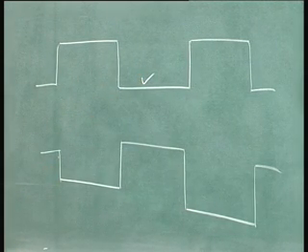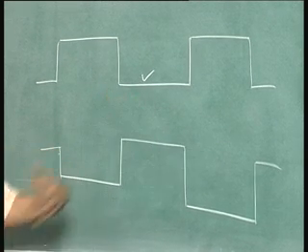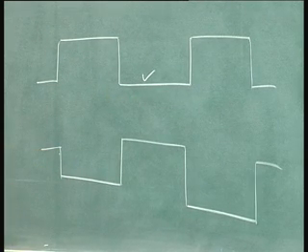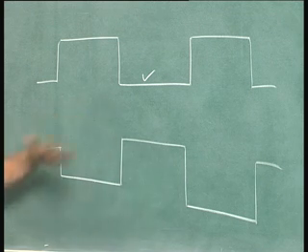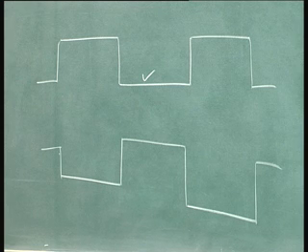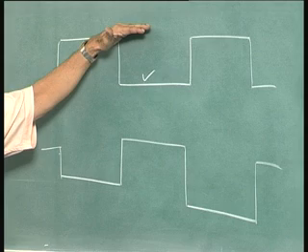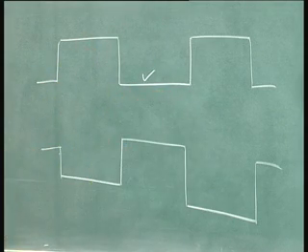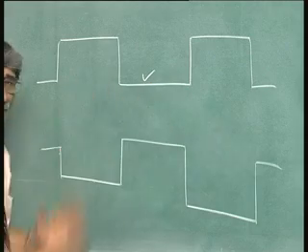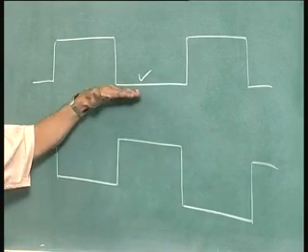And the entire energy band diagram now takes a new turn. In fact, I will discuss that in my next lecture. Today, I just point out, usually when you draw a conduction band, what is the meaning? Energy levels are continuous. Now, when you have a quantum, this well like this, potential well, and if this well is narrower, then you will not have continuous energy levels, both in the conduction band and valence band.